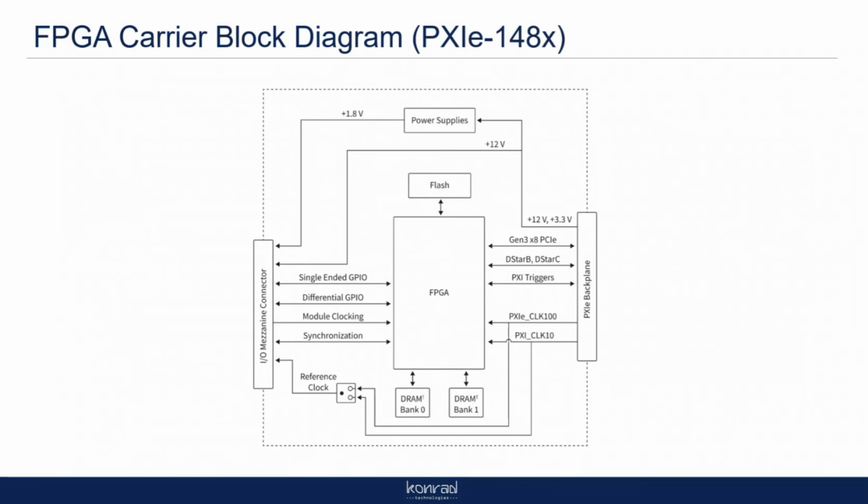So looking next at what happens on the FPGA, like I said, that's where we've now got the CSI2 data going into the FPGA. It's basically getting pushed into the DRAM and then pushed back up to us. And this is kind of the standard diagram, I guess, for all their FlexRIO cards, where they've got data coming in at this point and they're doing something with the data.